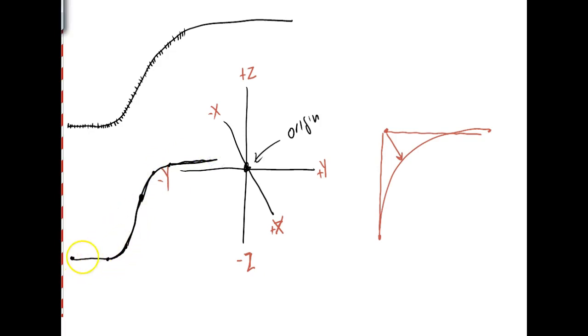And then I tell it how to move. As I program it, I tell it how to move. So that would be 1, 2, I'm sorry, I needed one right there. So that would be 1, 2, 3, 4, 5, 6, 7, 8 points that I would teach to teach that path right there.